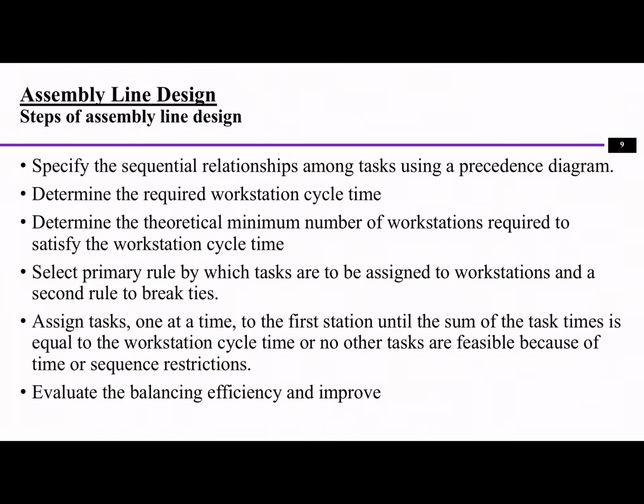Next, I want to talk about assembly line design. Assembly line design is more like the cycle time analysis, where we want to come up with an assembly line that is more efficient with the lowest cycle time, because sometimes you can group some of the processes or some of the workstations together. Sometimes we probably want to split the process in order to reduce the cycle time.